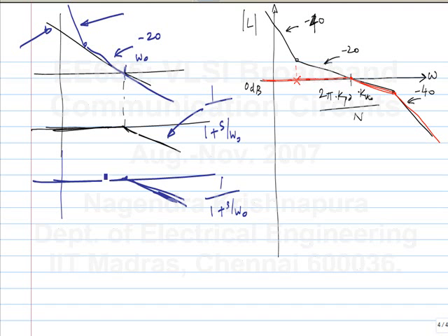What happens is there is what is known as a pole 0 doublet. Okay. So at the location of the 0 of the loop gain, you will have, I forget whether the 0 comes before the pole or after it, but they will be very close to each other. So when you plot only the magnitude, you don't see it. Okay. It looks more or less like a first order system, but in reality this will be this times 1 plus S by Z by 1 plus S by P, where Z and P are very close to each other, but they are not exactly the same.